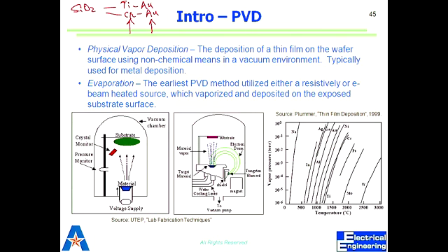I use special pumps, liquid nitrogen cryo pumps, which can really create ultra high vacuum. So when I melt it, number 1, all the vapors reach my substrate. Number 2, they don't have any contamination because I pumped everything out. We do this in a thing called an evaporator, but that top thing is called a bell jar.